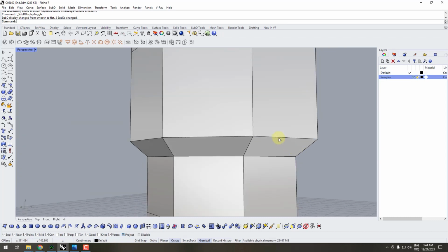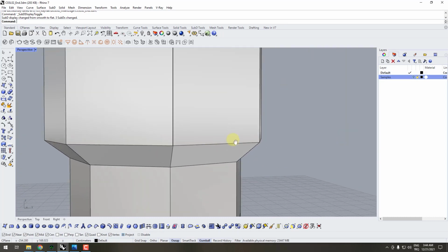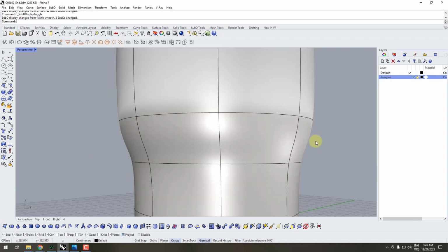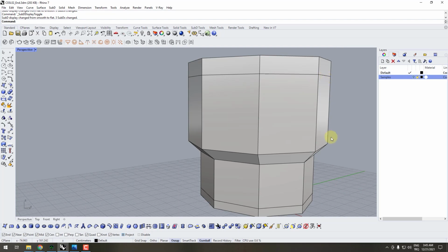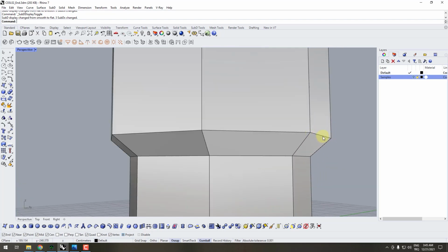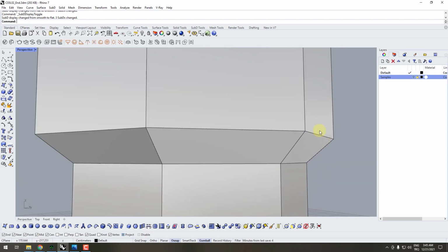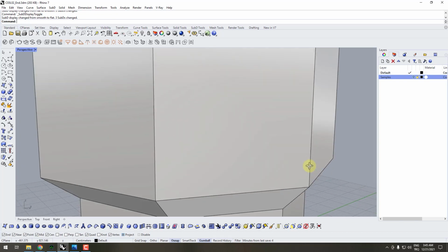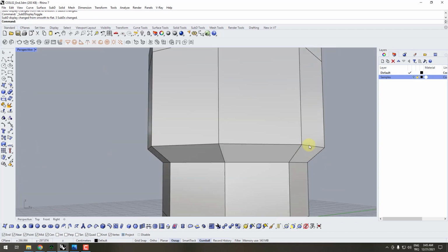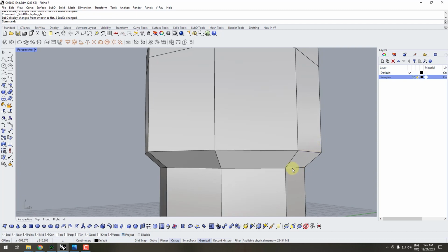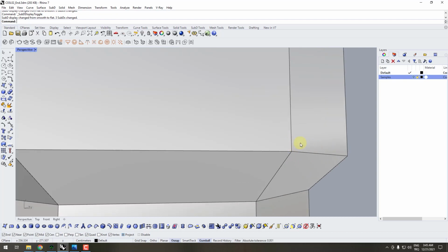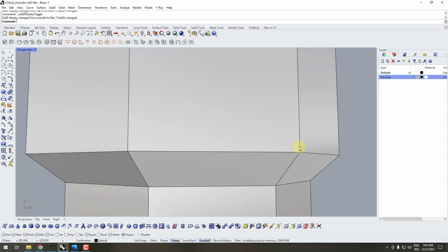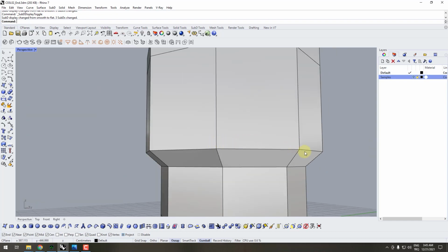As you know, when we create an edge in the non-SubD state of the geometry, SubD smooths the edges until SubD sees another edge. So we have an edge here. The surfaces next to this edge are not aligned, and SubD tries to smooth it until it sees this edge here and this edge here. If you want to tighten this smoothing, if you want to create a really tight fillet here, we need to create an edge loop in this area and in the lower area.